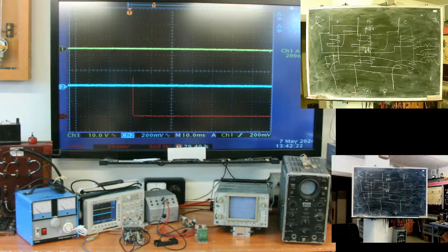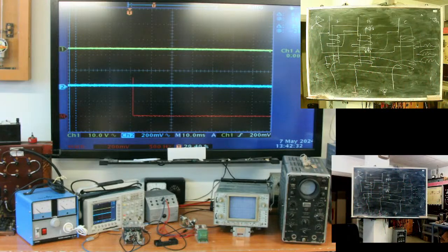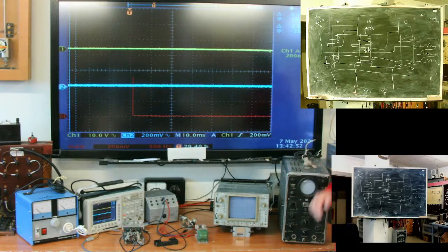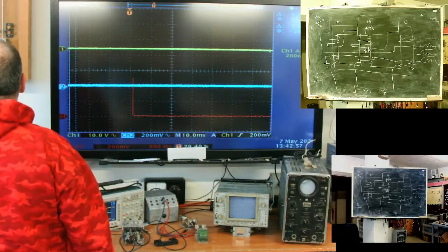If there will be any obstacle to the flow of this third harmonic, secondary voltage will be distorted, and we will possibly get problems. For a polyphase network, delta connection solves the problem even for isolated neutral networks.